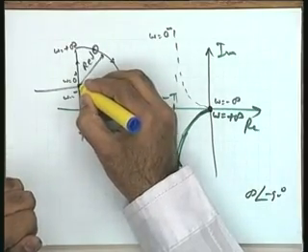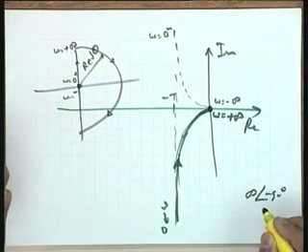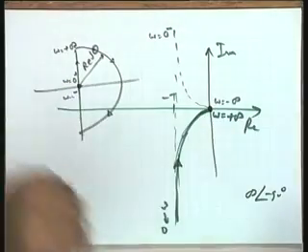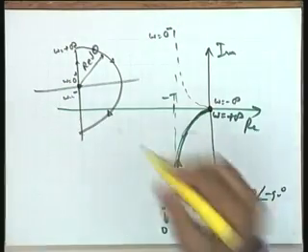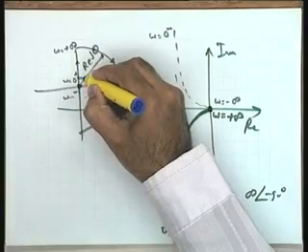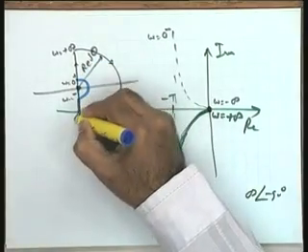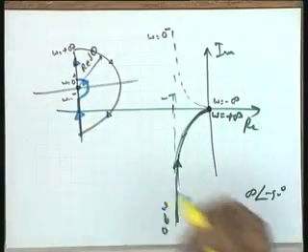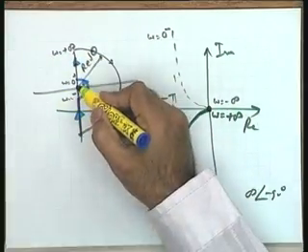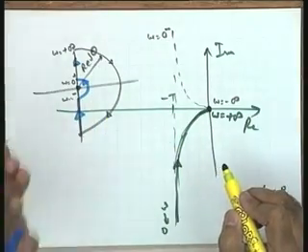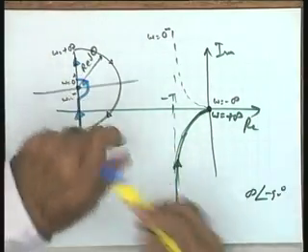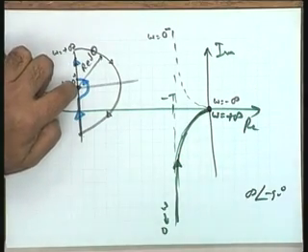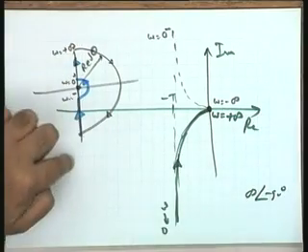You see, there is an open loop pole at this particular point, and if you take the mirror image of the mapping of this point, it gives you infinity. So what I do is an indenting. I take this as the Nyquist contour, where this pole has been avoided by taking a semicircle with radius epsilon, where epsilon tends to 0. So if there is an open loop pole on the imaginary axis, in this case it is at the origin, it could be at any other point also.